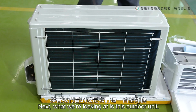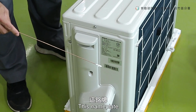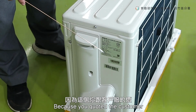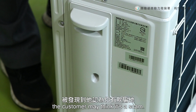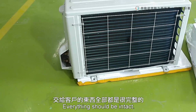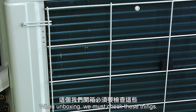Alright, next what we're looking at is the outdoor unit. The outdoor comes with a label, this nameplate. So check if these specifications match, because you quoted the customer using these specifications. If the product doesn't match the specifications, the customer thinks it's a scam. Next, check the appearance. Everything should be intact. Also check the fins. Sometimes production and packaging can cause damage. When unboxing, we must check these things.